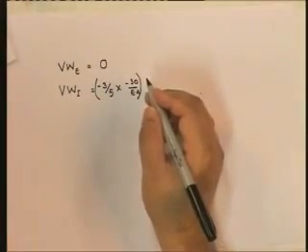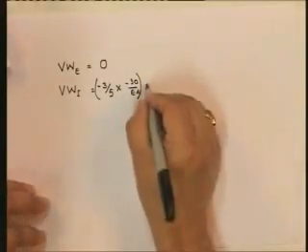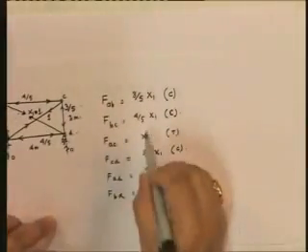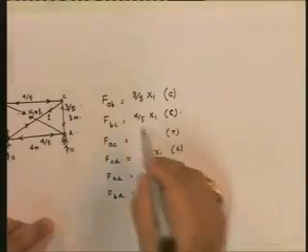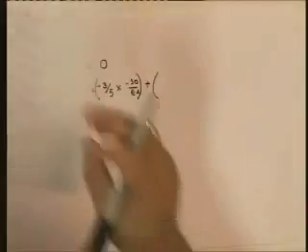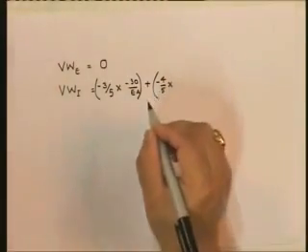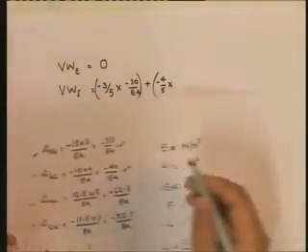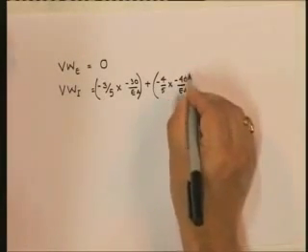Now let's go from AB to the next member, which is BC. So let us look at BC. What is the virtual force in BC? The virtual force in BC is 4 by 5 compressive, if we put a unit force. So that's going to be minus 4 by 5 multiplied by the real displacement, which is minus 40 upon EA.